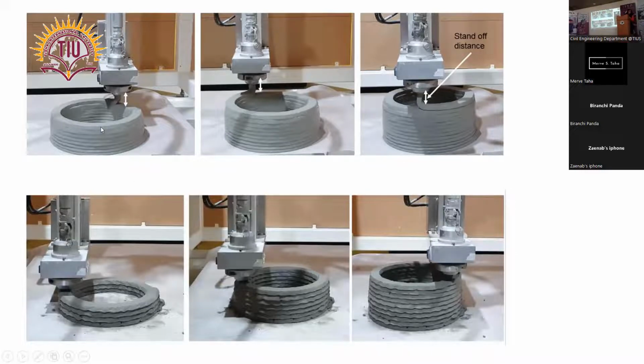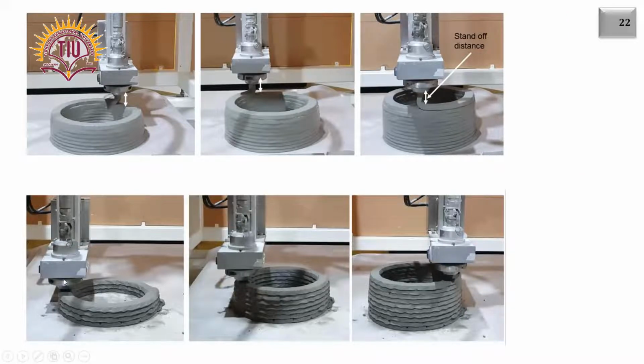You can see that this is an old geopolymer, and we modified it using some chemical admixtures, and you can see that there is no deformation during printing of the same design. Previously it was slumping. You can see there is an indication of stand-up distance. It means if you print slowly, the entire structure is going to collapse.